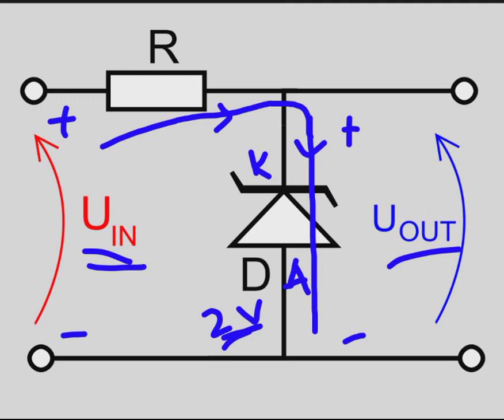So this is how your Zener, when it conducts current in reverse bias, maintains this 2 volt across the output terminal, provided your input voltage must be greater than 2 volt, because there will be a small voltage drop across the resistor also.